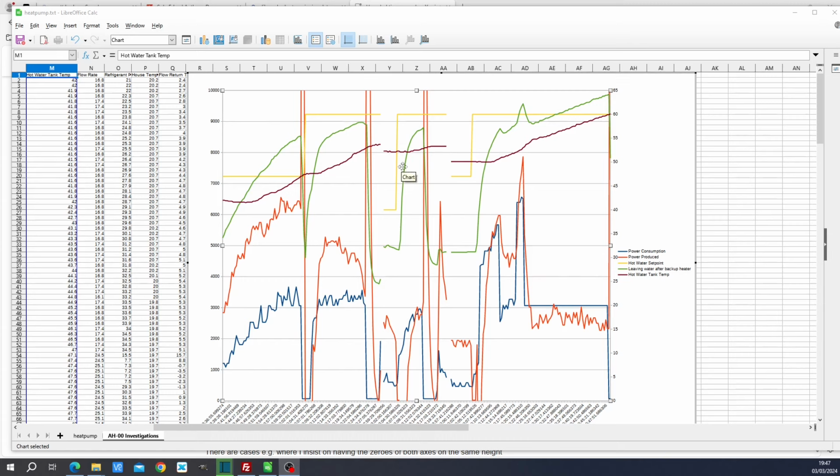Again, you can see the power ramping up to 3000 watts in terms of input, and in terms of output, we get quite a sluggish response. But you can see that the temperature ramps up to precisely 52.8 degrees Celsius before the compressor cuts out. Now, 52.8 degrees Celsius for hot water in both instances does not sound like a coincidence to me.